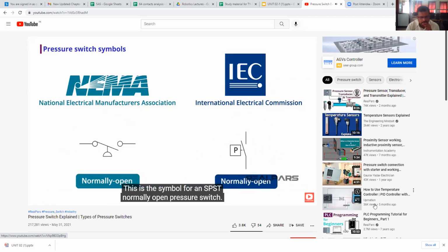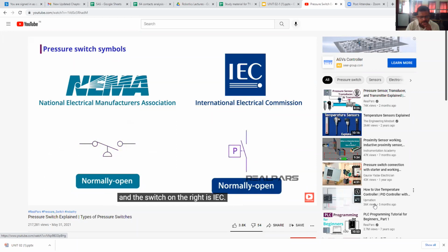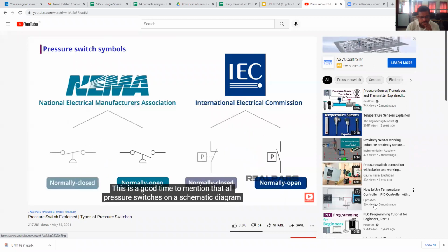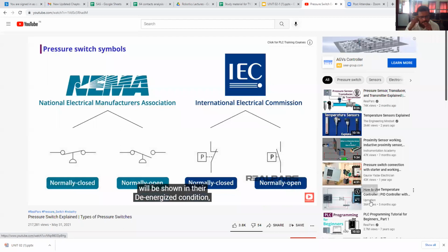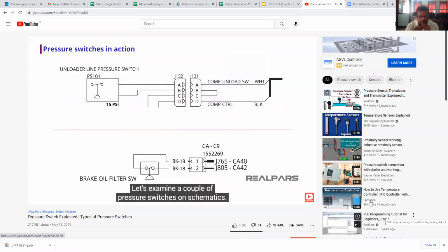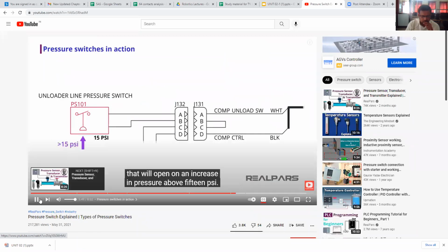This is the symbol for an SPST normally open pressure switch. Once again, the switch on the left is NEMA, and the switch on the right is IEC. This symbol indicates that the switch will close with an increase in pressure. This is a good time to mention that all pressure switches on a schematic diagram will be shown in their de-energized condition, or in other words, the condition they would be in sitting on a shelf. Let's examine a couple of pressure switches on schematics. ES101 is a normally closed switch that will open on an...